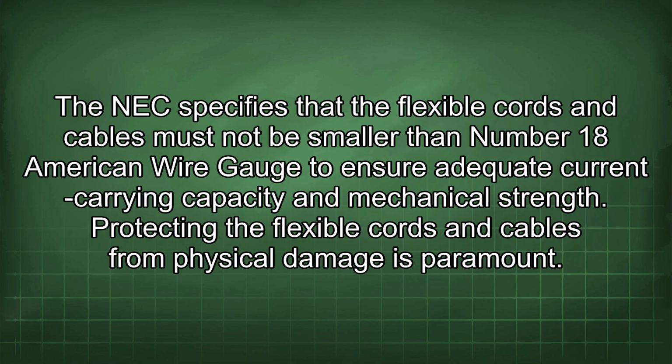The NEC specifies that the flexible cords and cables must not be smaller than number 18 American wire gauge to ensure adequate current carrying capacity and mechanical strength.